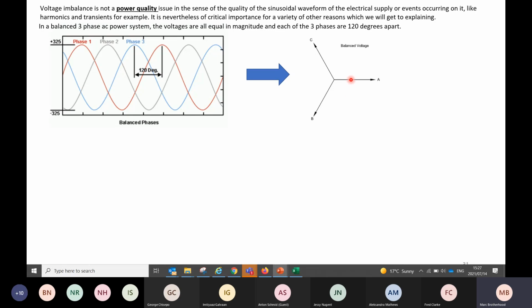We'll also know if I take a protractor and I put my protractor here, there's 0 degrees, and I measure there to there, hey, like 120 degrees, here to here, 240, 240, 360. Wow, this is spinning perfectly. It's nice and balanced. My pressure is nice and equal. The lines are the same length. And also the spacing between the lines, the vectors, is nice and evenly spaced.